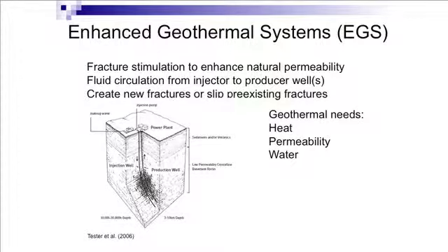So in granite, there's almost always pre-existing fractures, and they would like to slip because they're under a lot of stress, but there's friction resisting that slip. So when you increase the fluid pressure, you weaken the strength of friction, you can allow them to slip, and when they do, it increases their permeability, the ability for water to flow through those cracks. And so those are the two possible things that can happen in fracture stimulation.